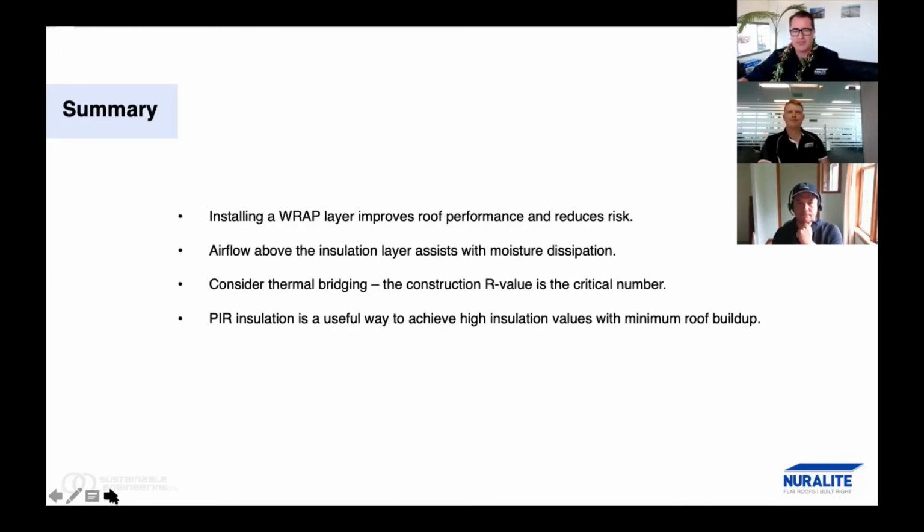Actually, we've just seen a question come through around penetrations, skylights and things like that. So Peter's software is a simple two-dimensional snapshot. Would that be fair to say of the roof build-ups? Yeah, and it makes it quite difficult for that last example because they'll have thermal bridges through the metal supports for that top skin, but they're only periodic. The only way I can look at it is one of your materials has to go infinitely one way or another. So there has to be a continuous line of a purlin or something like that. So skylight penetrations can be quite difficult to consider.